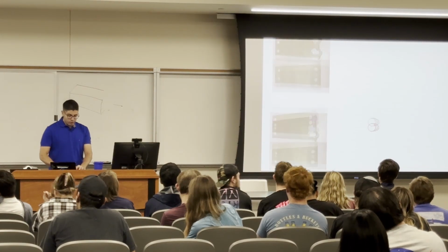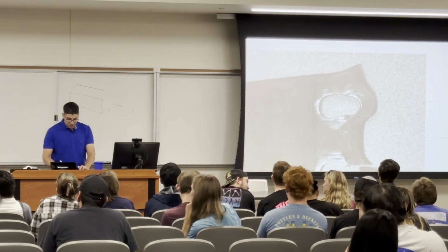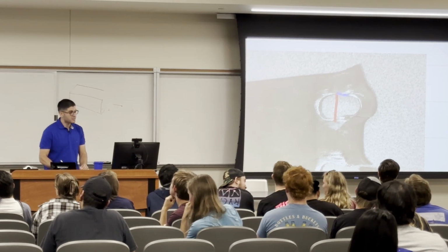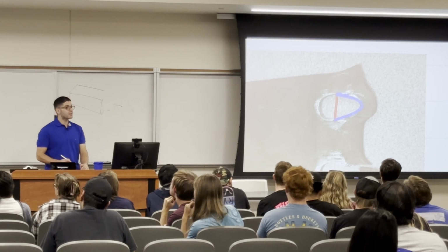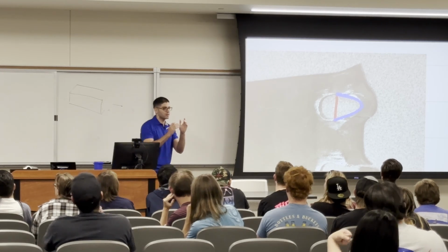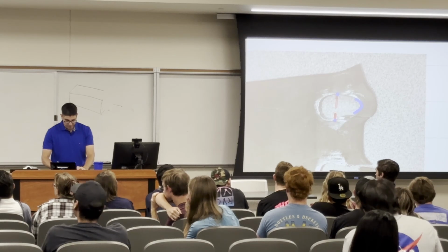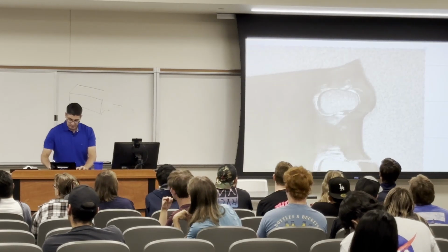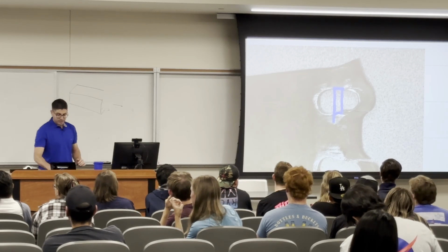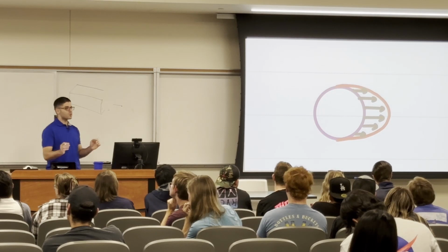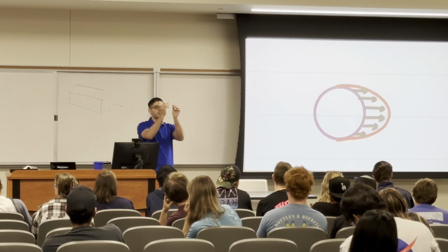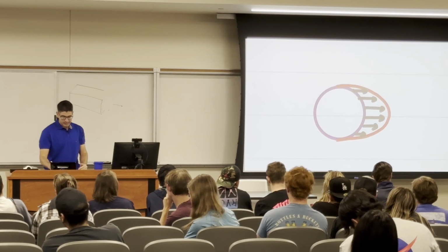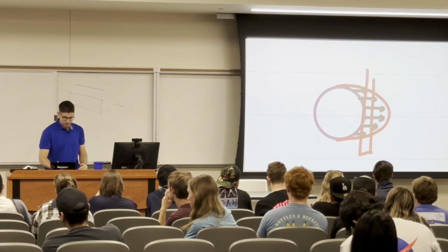Look at the failure. The failure itself wasn't constant. You will find that the sides felt zero stress and the stresses peaked in the middle. So this wasn't a uniform stress. It wasn't constant. I would agree with you to take the circumference area if the stress was uniform. But if I am to draw the stresses, it's going to be something like that. At the sides, it's zero, and it's picking up until the middle, and the middle is the peak. So because we don't have a uniform stress and it's not constant, we instead are going to take some sort of average of this.